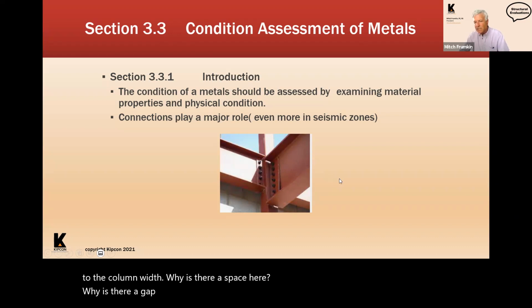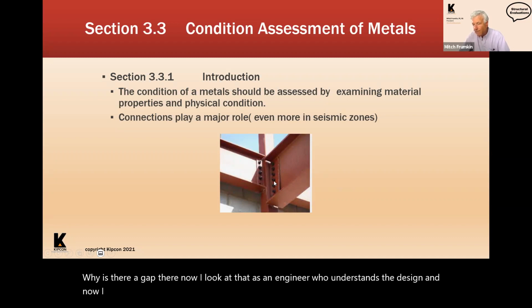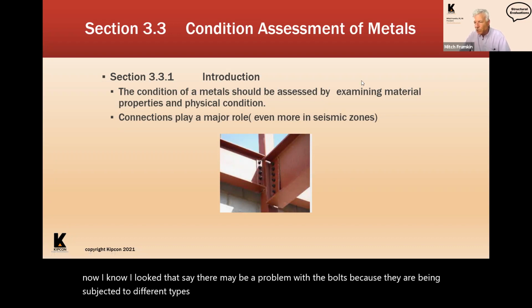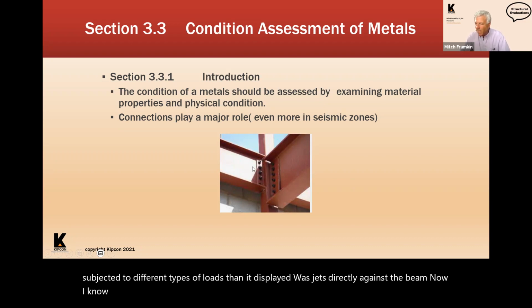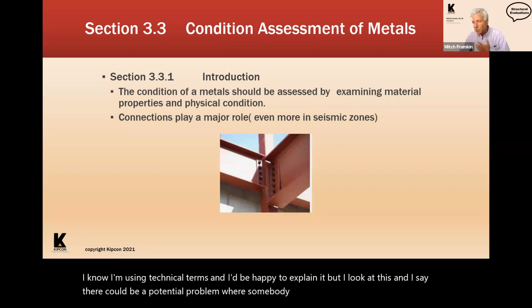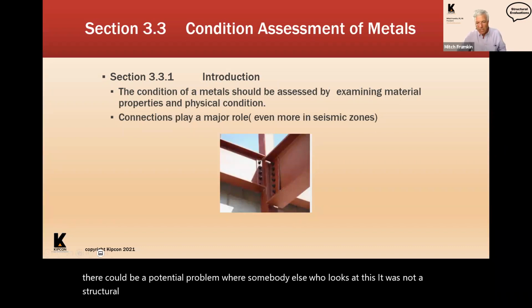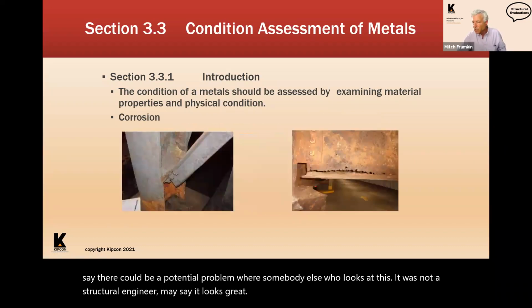Now, I look at that as an engineer who understands the design, and I say there may be a problem with the bolts because they are being subjected to different types of loads than if this plate was just directly against the beam. Now, I know I'm using technical terms, and I'd be happy to explain it, but I say there could be a potential problem, where somebody else who is not a structural engineer may say it looks great. So connections are very important.